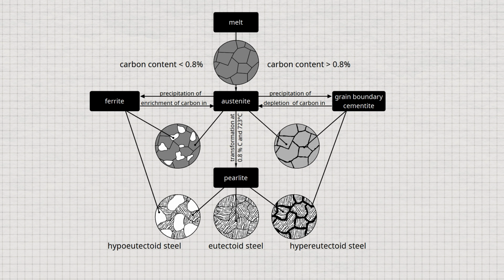The microstructure of a steel always consists of two phases, ferrite and cementite, whether it is a hypoeutectoid, hypereutectoid or eutectoid steel. Only the way in which the cementite is present in the microstructure, for example in pearlite or at the grain boundaries, differs. The determination of the exact microstructural proportions of pearlite and ferrite, or pearlite and grain boundary cementite, is explained in the following.